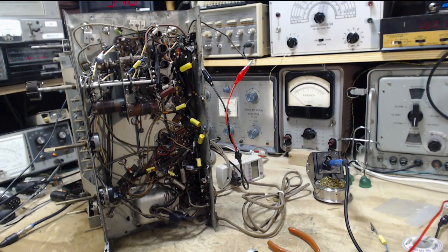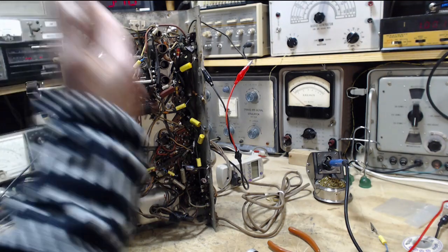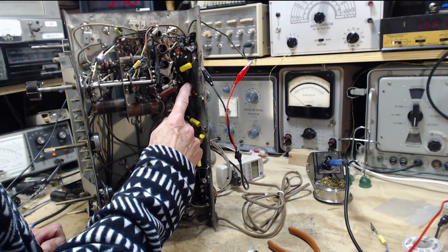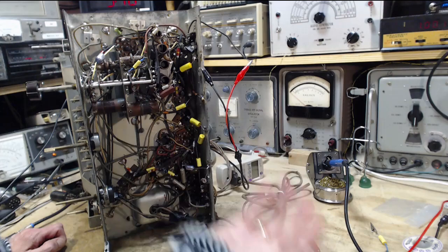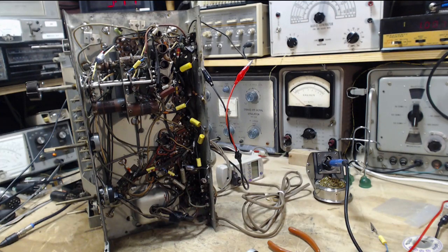Okay, let's fire up the radio and see what we got with this new capacitor here. Might be in for a very pleasant surprise. Oh, okay, the cats may have confused me a bit on the video here. I may have made a video recording error, so I'm just going to repeat something. And that is, I'm going to check for the voltage on either side of this resistor. One side should be B plus and the other side should be somewhat reduced voltage for the screen circuits in the radio.